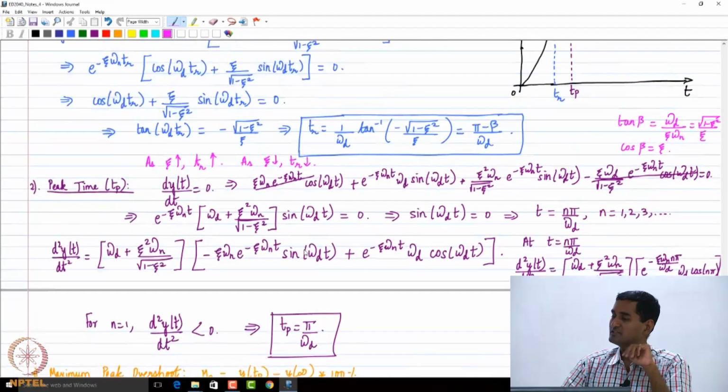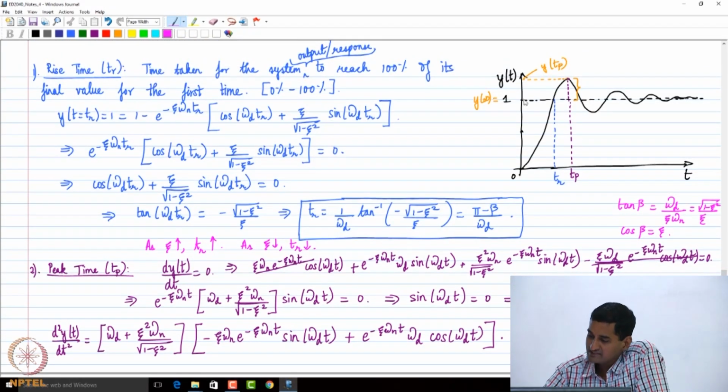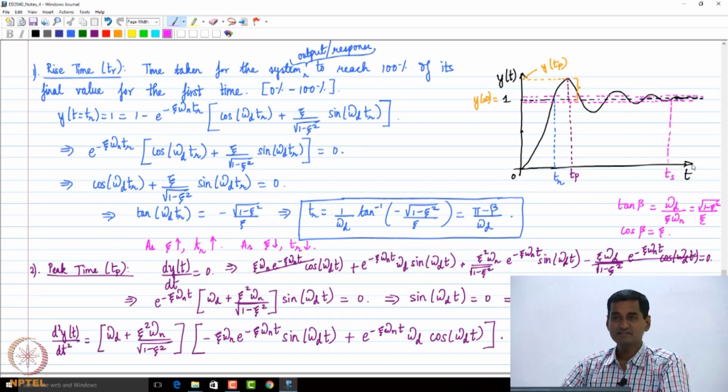So once again, how do we visualize settling time? Let me go back to this graph. Let us say I take the 2% band. What happens is that I draw the upper limit and the lower limit using this pink dotted line, and then you figure out what is the time after which the output settles to within this band, right? That's my settling time. Is it clear? I hope it's graphically also clear as to what we define by settling time, right?